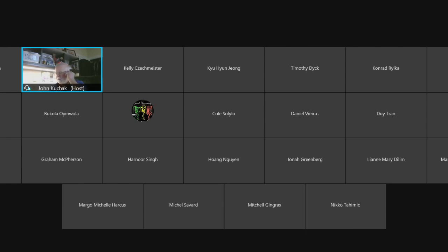We're going to look at a video here where they're going to be testing concrete, and they're going to use steel caps with neoprene inserts. We don't do that here. We grind our cylinders to the same tolerance. From a private point of view, like a ready-mix producer, if it's his own data, he can use caps.